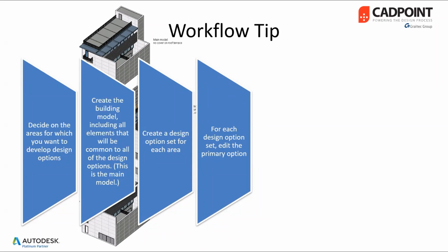It will be displayed in the project views by default. Other design options will appear in views only when you specify. Edit the primary option to add elements to the design as desired.